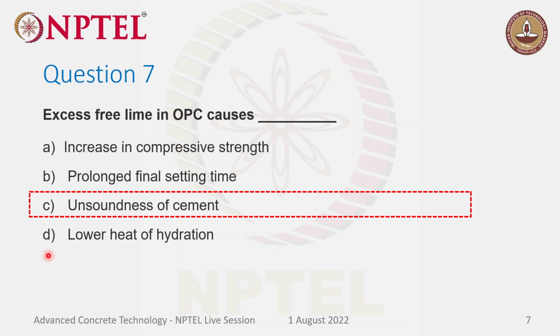You're saying the chloride limit is 550, right? My question, madam, is that I observed white patches on the cube's outer surface. Okay, fine, it's called free lime or something else. If there are excess alkalis, this can also be possible. If the water has some alkalis, then it can also be one of the reasons.